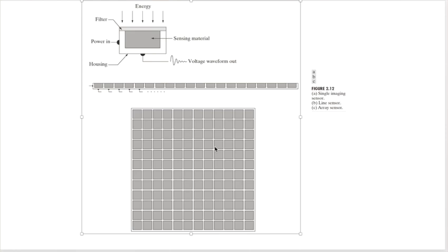They do. So they have these machines. Have you ever seen the machines running them through? They'll have a single one of those line arrays. They know how fast it's feeding. So they'll just take pictures really rapid out of it as it's going by. And they know the speed so they can reconstruct the 2D image. And they never need to stop. They just take the pictures really fast line by line and it just assembles them up because you know how fast it's moving.